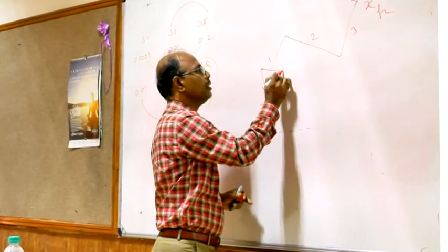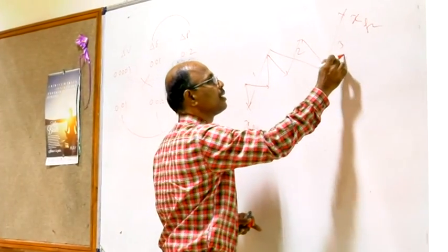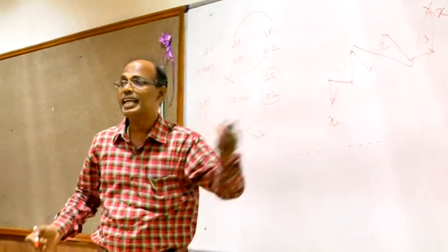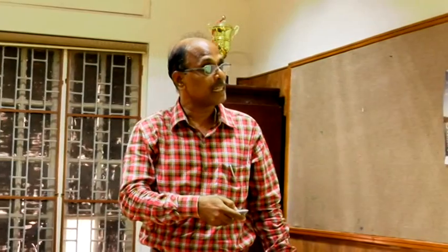Again it gives a wrong direction, then it moves here, then here, like this. Finally it reaches. So instead of 3, it takes 7 or 8 iterations to reach the final point because we made approximations in the Jacobian matrix and removed two portions. That's why it takes more iterations, but still takes less computation time. Okay, this is called the decoupled Newton-Raphson method.